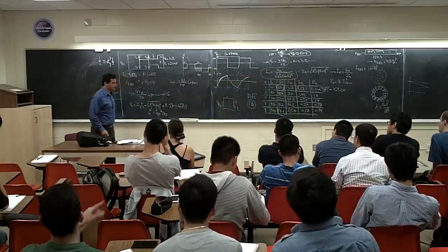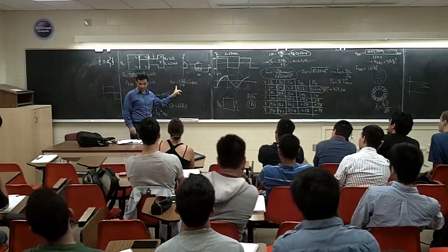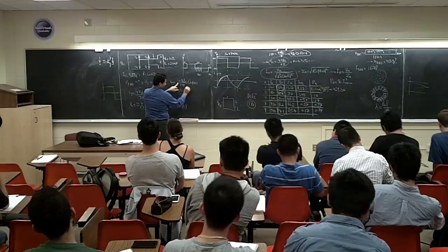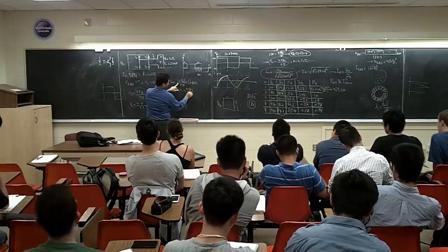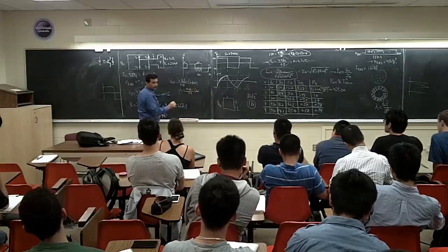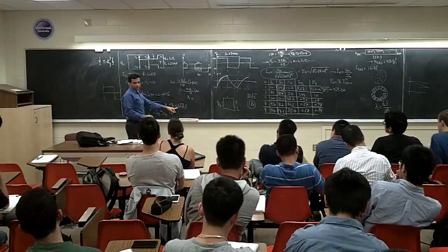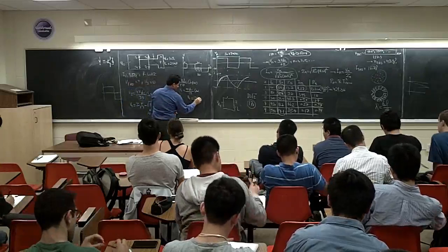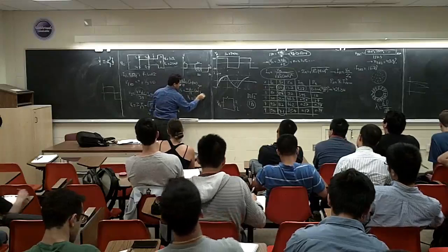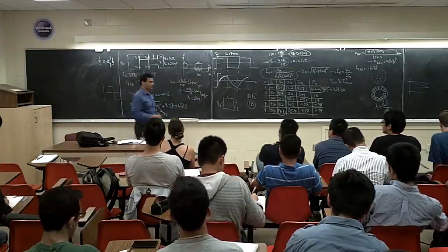Now, what should I do next? Plug into the equation. To which equation? For VDC. Both sides of this equation. So how much is V1? V1 is going to be 4 VDC over 3 pi cosine of alpha, right? And also, I know V1 should be 127.3, and this alpha is 30 degrees. Just put these two equal. From these two, you can calculate the VDC. How much is the VDC? 116.